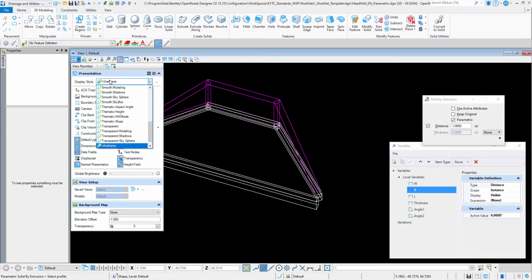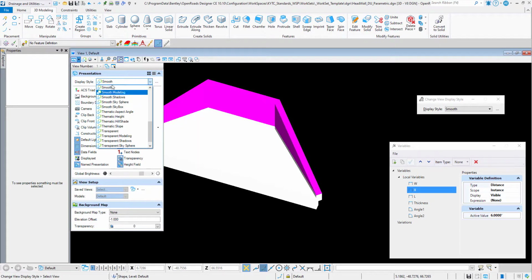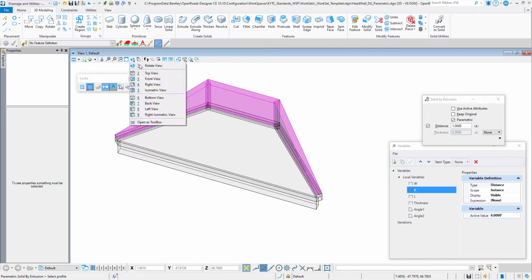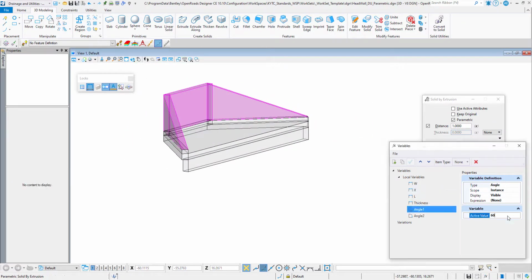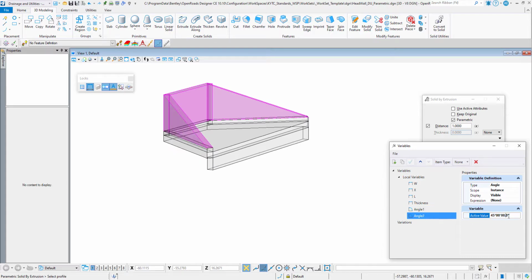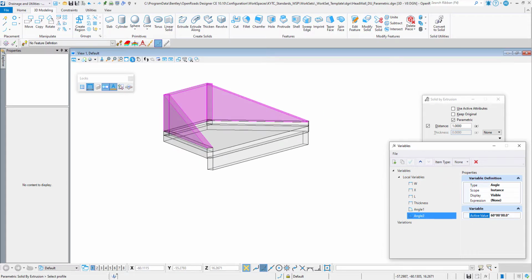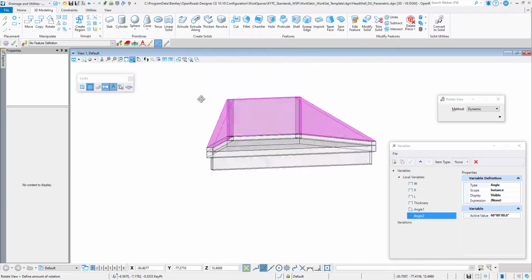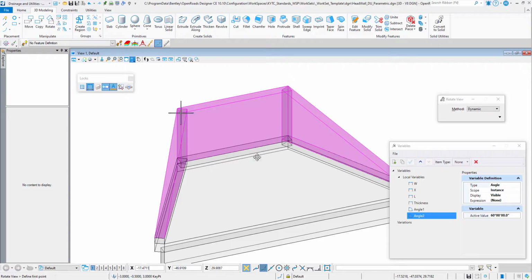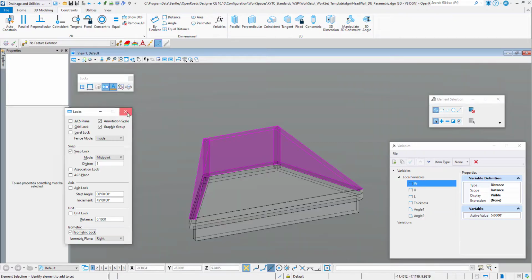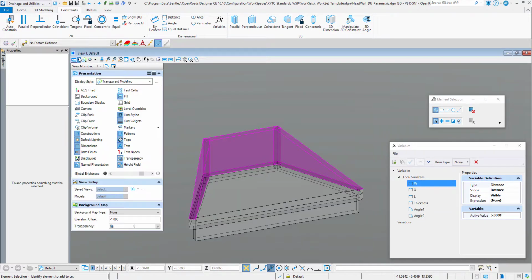Now, one of the things that I'm missing here is that if I happen to change any of my thicknesses, or if I created a parametric constraint that is going to change the value of the bottom piece that moves up and down, this toe is not appropriately constrained. But in this example, I will never use this for a cell that will expand that bottom piece. So I don't need to constrain it. But if I wanted to, I could have constrained the surfaces to touch each other using the 3D coincident constraint.